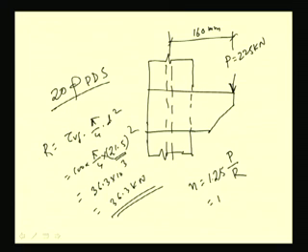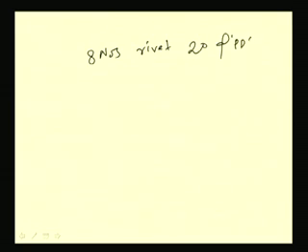So, this will become 1.25 into P, which is 225 kilonewton, and R is 36.3 kilonewton. So, this is coming around say 7.8, that means 8. That means from load point of view we can use 8 numbers of rivet with 20 mm diameter, power driven soft rivet.